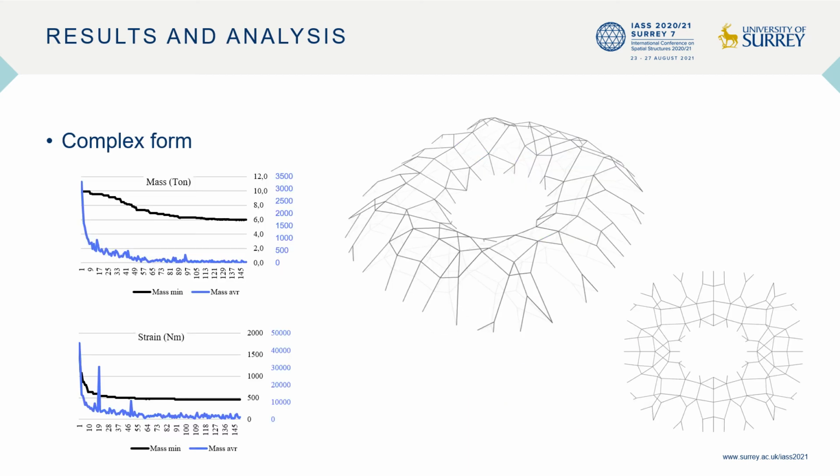This case was examined to see how the algorithm would perform on a more complex base shape. The algorithm created these braced legs to transfer the forces to the ground, but one can also notice some vague arch configurations within the grid topology. The bending energy in the grid contributes with roughly 37% of the total strain energy, though some of this could originate from the unorthodox shape. The solution still exhibits good membrane behavior.